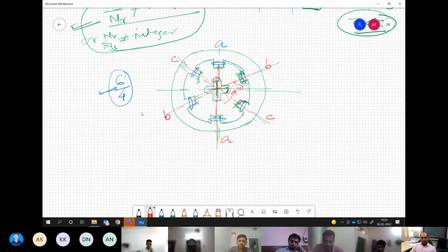So this is a kind of three-phase SRM. It has three sets of coils. At any moment, one set is aligned, one is going to be aligned, and one is going away. Are you able to visualize that? Yes, sir. Fine. Now, when you have 6 by 4 or 4 by 6, this kind of arrangement, even if this is aligned and stuck over here, the next moment you excite B and remove excitation A, this will have a tendency to automatically move. Understand my point? Which was not there in the previous case.